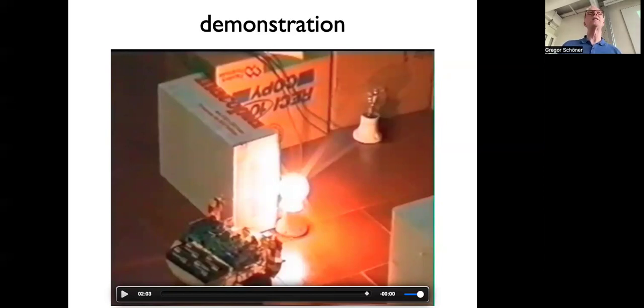we would say, well, if there is something close on the right, I want to turn left. If there's something close on the left, I want to turn right. Pretty much all the algorithms they had were some variation of that, some using neural networks and some using other kind of math, for fuzzy logic, and all kinds of approaches. But the functional idea behind it was ultimately that. And you can see that that can create an attractor in a corner.